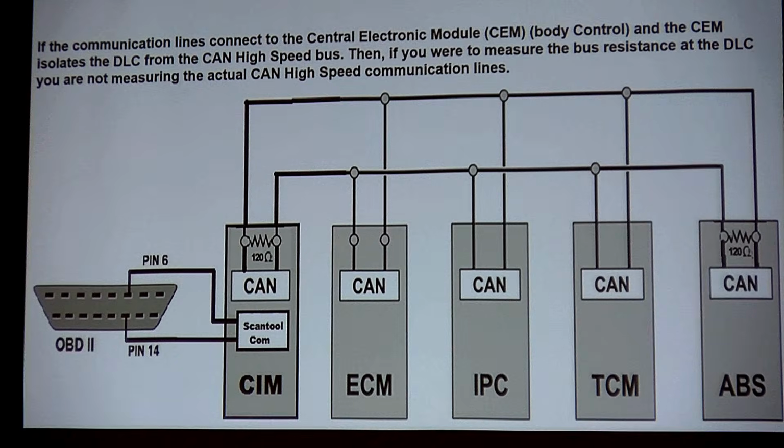I want to make a note that you guys absolutely need to listen to. When you see a scan tool where you're not communicating on that bus, but you're communicating with a SIM, you may not have termination resistors, guys. That module blocks you from it. If you've got a Jeep Chrysler product, they block you. The front module, you're not on the bus. Let me be clear here. Those wires, when you plug your scan tool on, you are not on the bus. You are isolated from the bus. You are using the bridge mechanism to bridge your scan tool onto it. That means if I plug into the DLC with a scope, I may not see what's happening on the bus. I see what's happening between the microprocessor and my scan tool. That is not the bus.